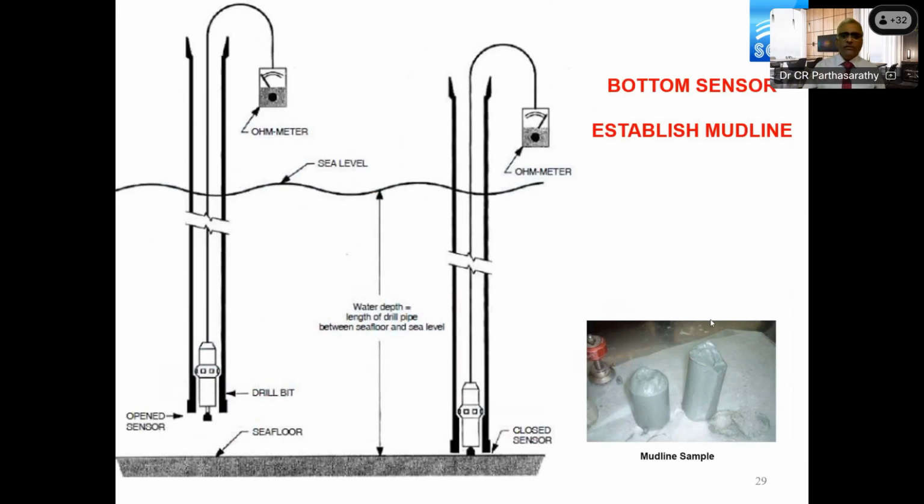Okay, so how to establish the mudline? There are different ways of doing it. One is to get the water depth and collect the samples, and if you're able to see the samples at the water depth that you know from the bathymetry, then that's the mudline.